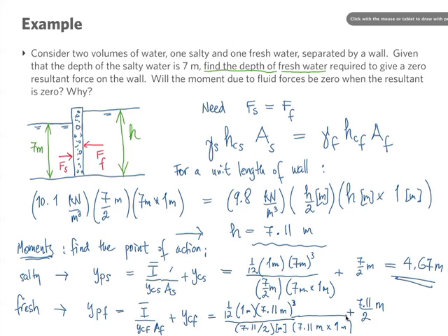Again we have everything, and we can calculate, and somebody there is checking my arithmetic, and he agrees. For this one I get 4.74. So like we expected, the points of action of these two forces are not the same. So there is a moment. Even though the forces are equal on both sides, there is in fact a moment.